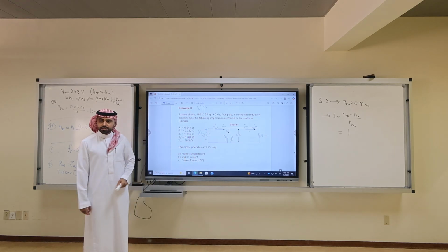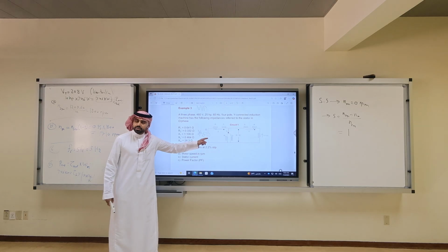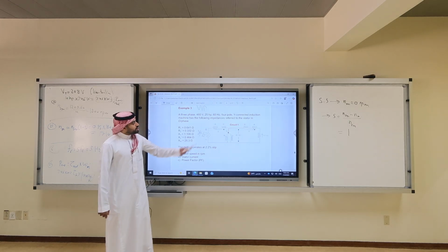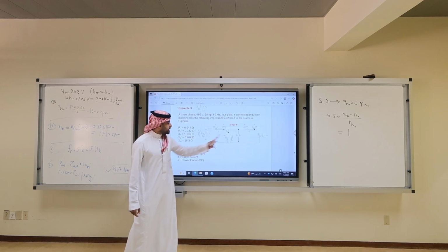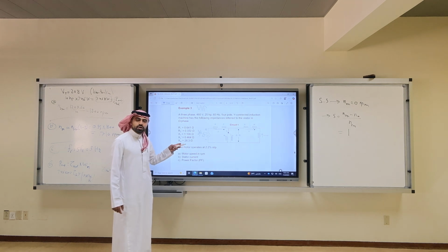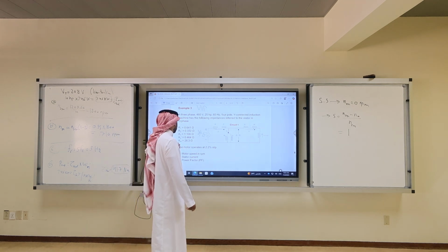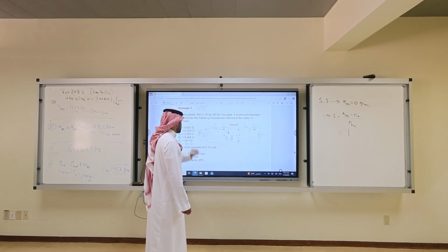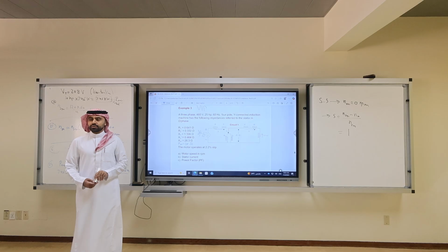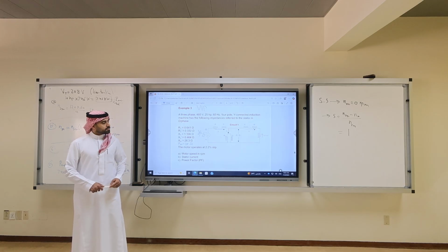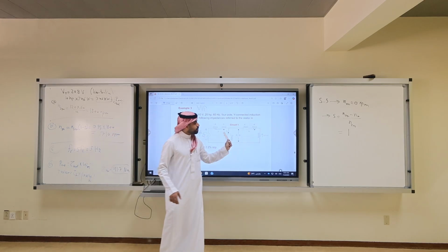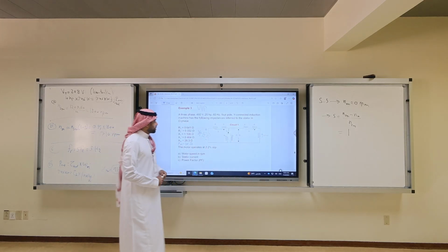This is AC source. Is this AC or DC? AC. What is R1 and X1? They are given. R1 .641, X1. What is RM and XM? RM, is it given? No. So assume it's infinity. Usually it's a big number. 100. 100 compared to 0.6 is a very big number. And when we do 100 parallel with small, it will go away.